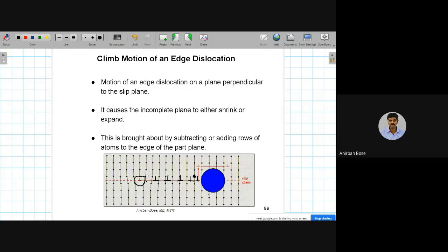Here in this diagram you can see this is a single atom, but actually if you think of the whole crystal, it is basically a set of atoms, right? If you visualize the basic figure with which we have given the examples, you will find that this is a set of atoms perpendicular to the slide. If this set of atoms somehow goes to some vacant place, you know that there are different vacancies present within the crystal. Suppose this region is a vacant region, some vacancy is there.